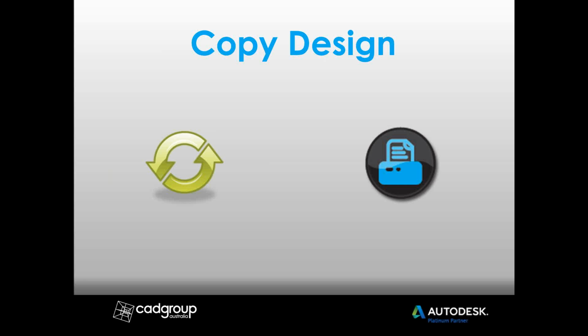Now, from within the copy design dialog box, you can choose whether you want to copy the design, reuse it, exclude or replace different parts. You can define a new naming scheme for the files in the new design. Alternatively, you can choose to add a prefix or a suffix to the new files automatically. If the original file names end in an integer, you can choose to automatically increment those names. You can also rename presentation files and drawing files to match the names of their direct part or assembly source.